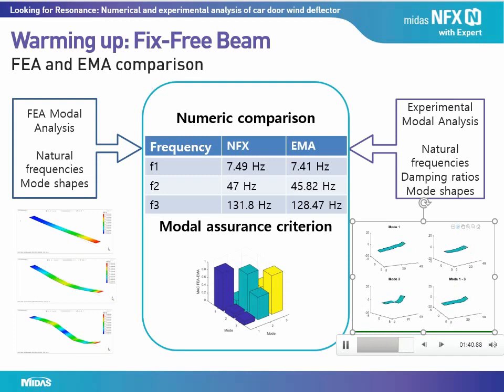Given mode shapes obtained numerically and experimentally, we can perform correlation among them. This is the Modal Assurance Criterion, MAC, represented by a matrix. In general, we have main diagonal values close to or equal to 1. Theoretically, other values are 0. Non-zero values of them could be due to measurement noise or insufficient response points measured. The MAC matrix visualized as a 3D bar chart is illustrated here.